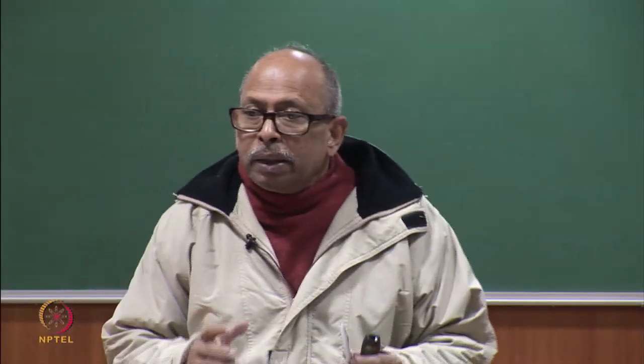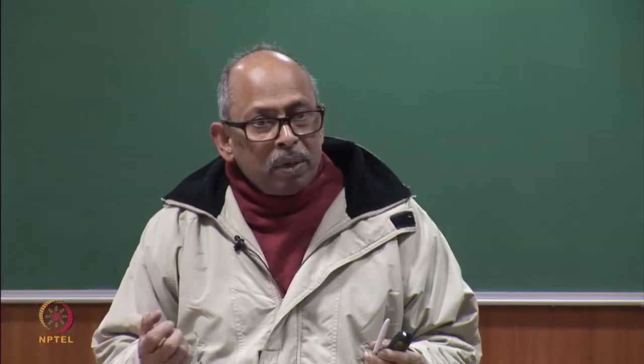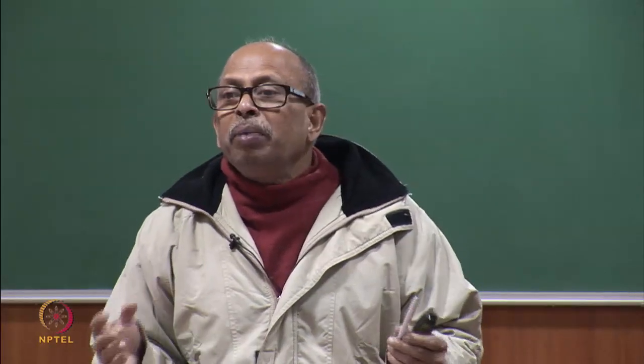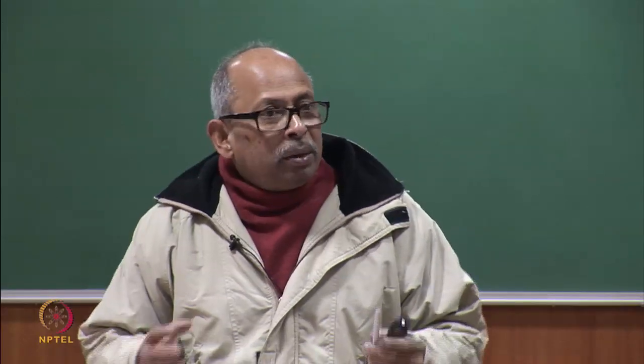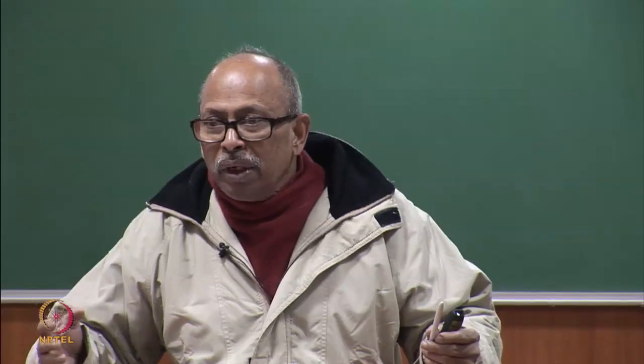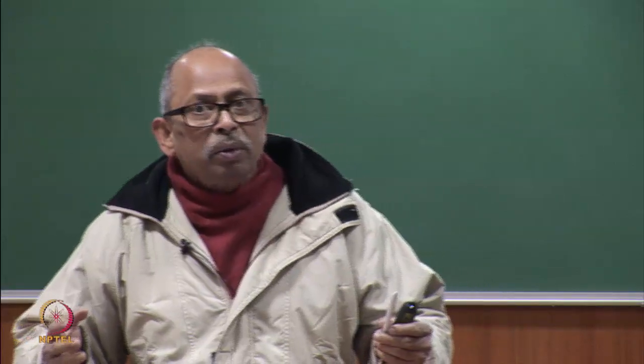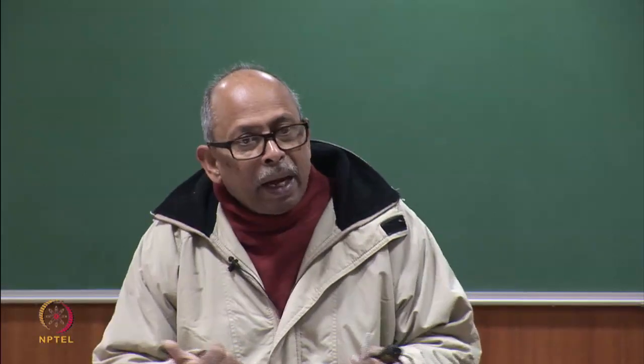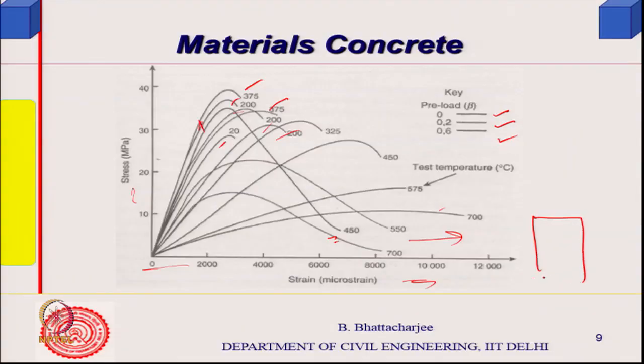Because now as you have heated it up and then, let us say, loaded it, lots of cracks have already formed. So, those cracks manifest themselves in the form of strain, right. Lots of cracks would have already formed, like tensile cracks would form in a compression cube like this. Normally when you load a cube like this, essentially Poisson's effect causes cracks to occur like this, it bulges out. So, this would have already occurred, then you have heated it up. So, now this means the compression deformation, because of Poisson's effect along this direction, there is a compression.